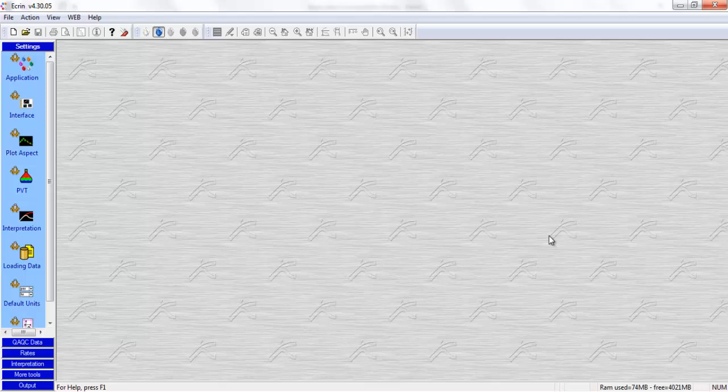The type of well, whether it's an oil producer, a gas producer or water injector. The PVT data, so formation volume factor, viscosity, fluid compressibility. The static data, so net reservoir thickness, initial water saturation, porosity, wellbore radius, the rate data, and the pressure data.